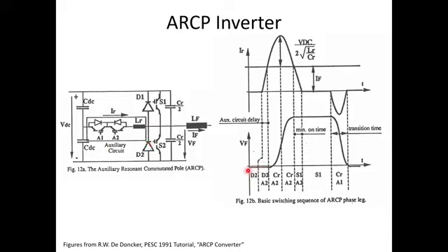And what you'll see is that when you trip the auxiliary circuit, you can go from the bottom switch being on to the top switch being on, and hence you can get very nice soft transitions, which helps reduce the EMI of the circuit and reduces the switching loss. Okay? There's all kinds of switching transitions to the circuit. You have to think about what's the load current and everything else to figure out what sequence of steps you go through to get between the bottom switch on and the top switch on, or vice versa.